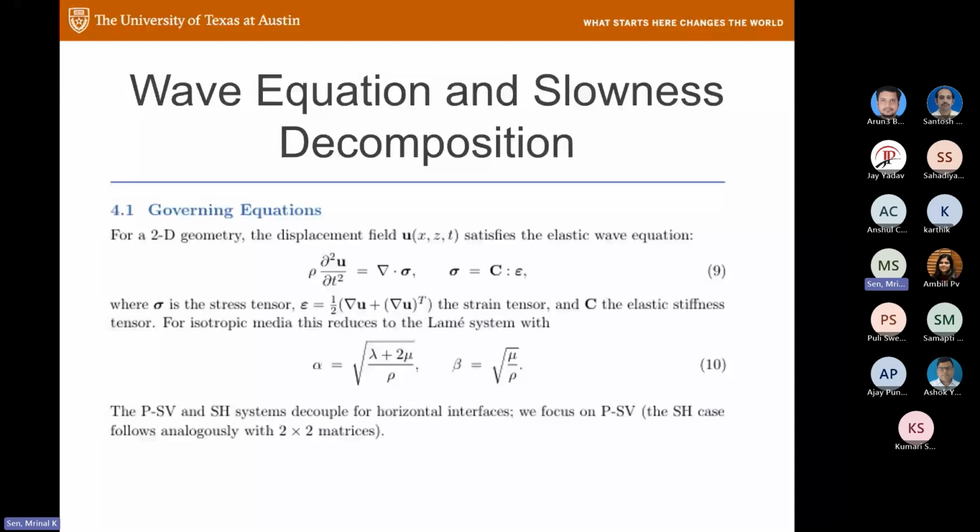So which equation is this? Anybody remembers? Speak up. Which equation is that? Wave equation. So this is Newton's second law, mass into acceleration, and this is your generalized Hooke's law. If you put the sigma term here, then this is a wave equation. But you can call it a wave equation, assuming that you are using this in sigma. So yes, but this is Newton's second law.